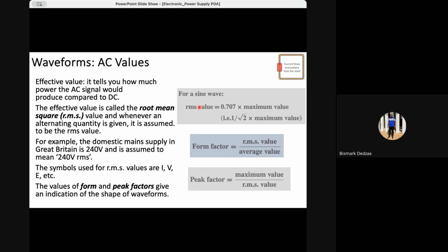Why the surge in that value before getting to our homes? What happened? Okay, so nothing happens. That is the actual value that it has to get to your home. Is that okay? That is why we are calling it the effective voltage. It's a ratio of the voltage that we want in terms of DC. So in actual sense, if you connect a meter to read, you will read the root mean squared voltage. But if you connect to an oscilloscope to measure the actual alternates, you will see the 300 and something volts, if you have to read the peak voltage.